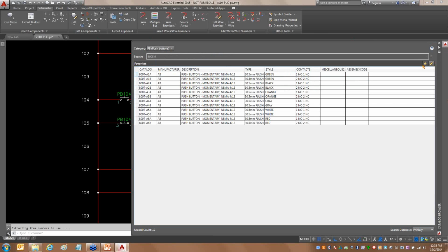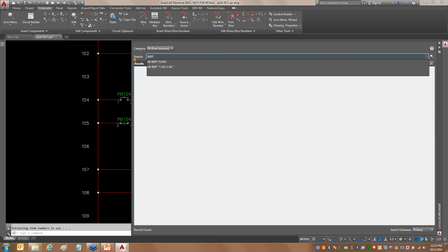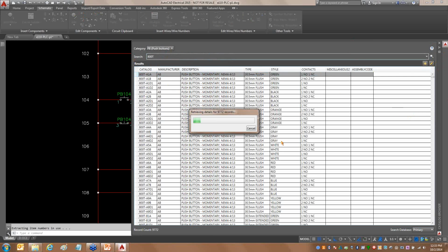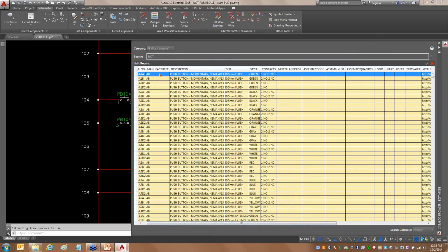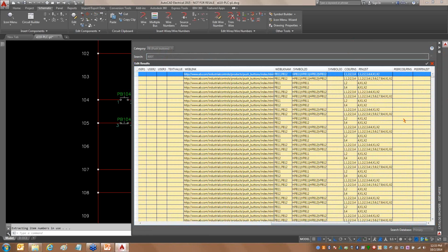It was just basically knowing the sequence and way that the Allen Bradley is naming their catalog information. I came up with how they were doing it years ago. And just to show you how I did all of it, I'm just going to hit the edit button here. Because out of the box, if I was just doing one, this is the way I would do it. I would just edit that entry and go all the way. There's no longer a pin list database editor. You would edit it through the catalog browser like right here. And you can see here all those coil pins and pin lists. Those are all blank before I ran that migration utility from that catalog.